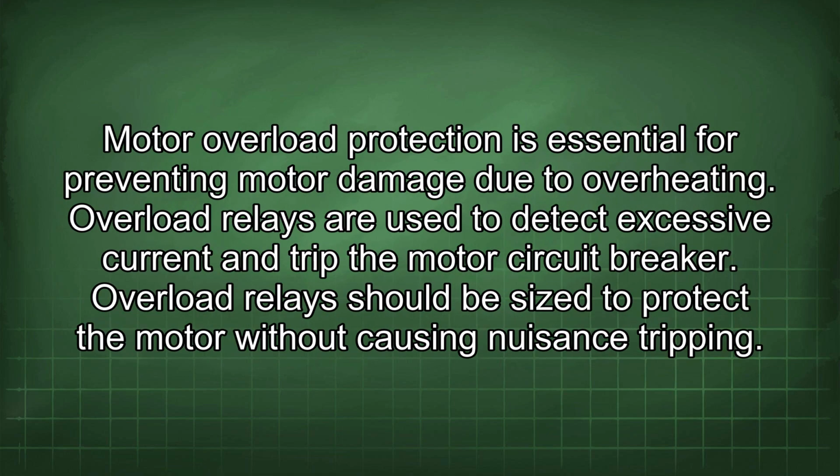Motor overload protection is essential for preventing motor damage due to overheating. Overload relays are used to detect excessive current and trip the motor circuit breaker. Overload relays should be sized to protect the motor without causing nuisance tripping.